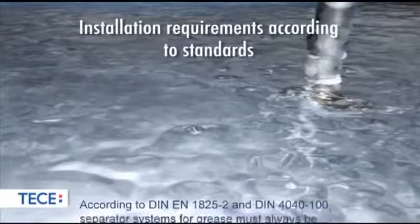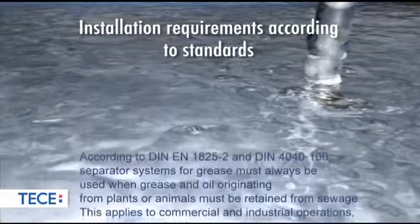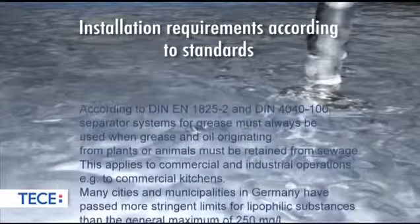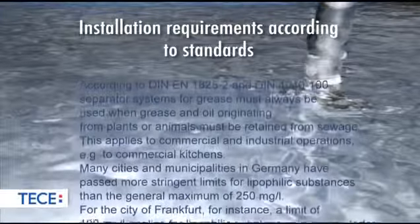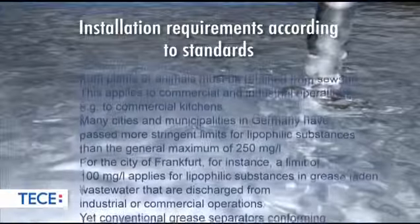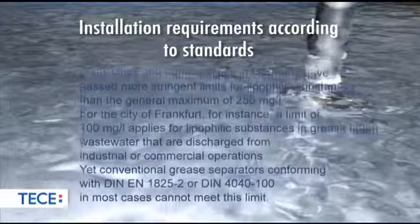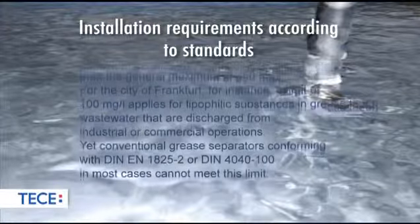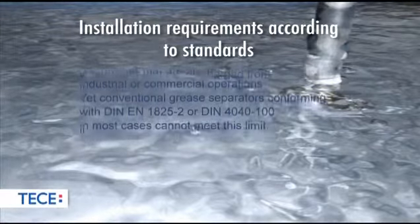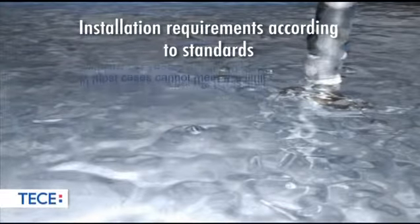What intake limitations apply to wastewater containing grease? According to DIN EN 1825 Part 2 and DIN 4040 Part 100, separator systems for grease must always be used when grease and oil originating from plants or animals need to be retained from sewage. This applies to commercial and industrial operations and to commercial kitchens in particular. Many cities and municipalities in Germany have passed more stringent limits for lipophilic substances than the general maximum of 250 mg per liter.